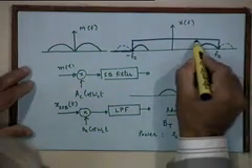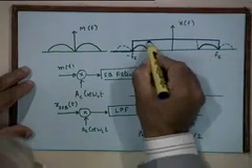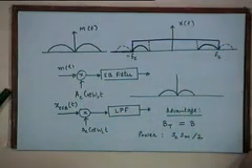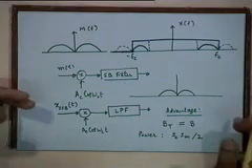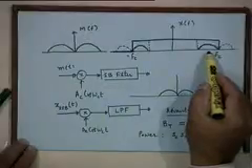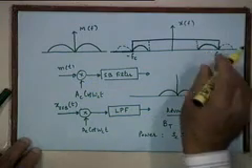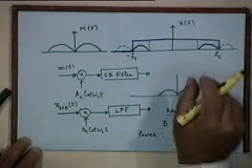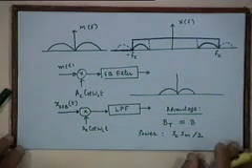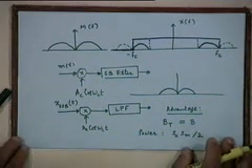In practice, of course, you will not realize a low pass filter, you realize a band pass filter, which will have this transfer function, but it will also be associated with the same difficulties, right? One can approximate such filters. Basically you require what are called high Q tuned filters, because typically these carrier frequencies are very high, and this bandwidth will be a very, very small fraction of the carrier frequency. So a narrow band high Q tuned filter will do the job, right?